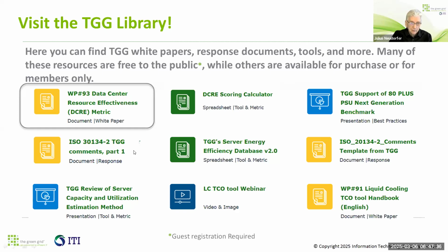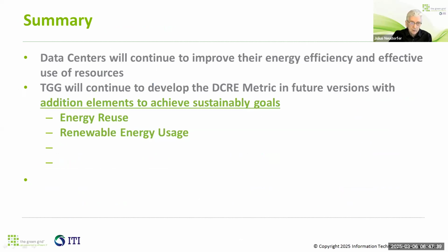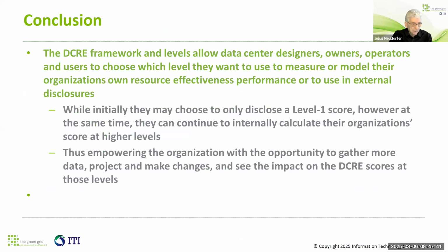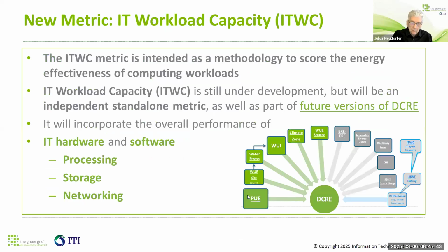In fact, I can go back a couple of slides here to see where we were talking about this. Just one moment. I know we have a couple of minutes. So PUE alone, coming out to whatever your IT is, if you ignore everything else in here, is as valid today as it was tomorrow or anything else. It's a facility energy effectiveness. What are my transformer losses, my wiring losses, my cooling losses, lighting, you name it, PUE is saying total input against the IT energy, respectfully.